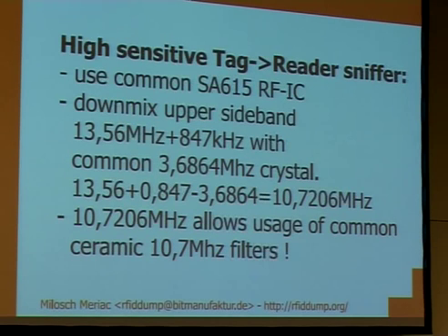The magnetic loop antennas you can buy freely are used for sending also. You need very expensive adjustable capacitors for this kind of antennas because we have very high voltages when sending. But we only want to sniff passively, so we can use cheap capacitors, and it's very simple to build a homebrew loop antenna.